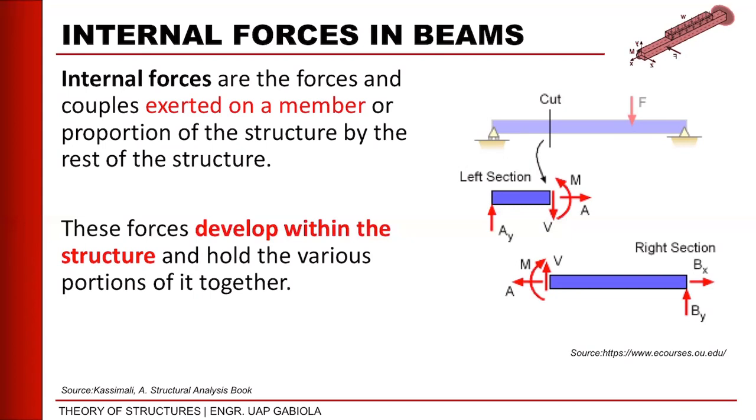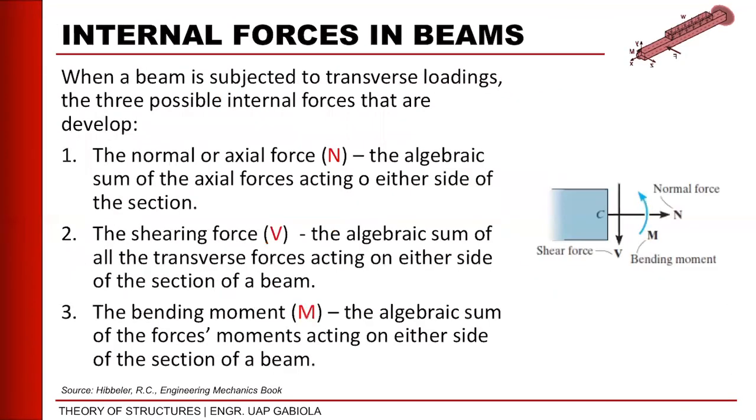Okay? And then, when a beam is subjected to a transverse loading, three possible internal forces are developed. So ito na, papangalanan na natin yung mismong forces na tinutukoy natin as internal forces. These are the normal or axial force, the shearing force, and the bending moment.